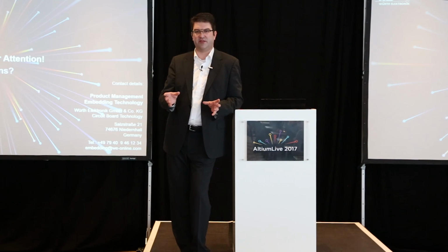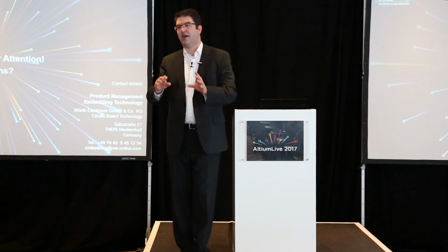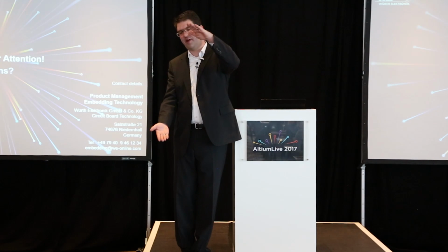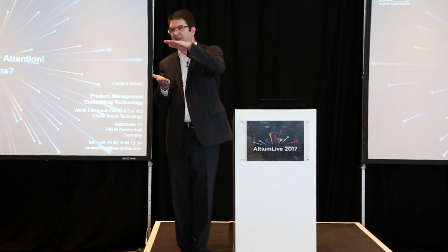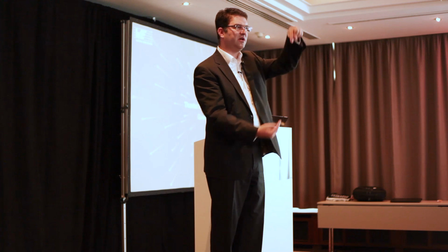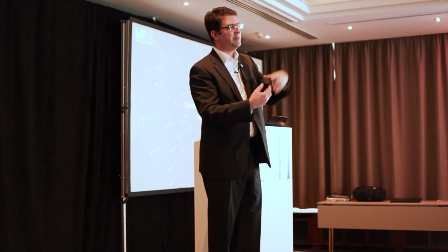If the die, for example, has copper on the front and the backside, and you have only that die, so you can have a very tight tolerance and a tight planning in your core, you can actually connect it on both sides with microwires. Another thing you can do is, for example, placing the component on a very thin core.